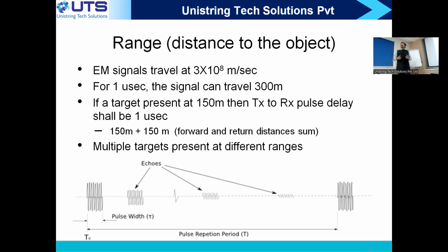At the same time, the more challenging part is that, in addition to targets, there is an annoying, disturbing background, which we call clutter in radar. To handle this clutter and multiple target detection, we get into the signal processing algorithms of radar. Otherwise, a simple time delay measurement would be enough: I send a pulse, receive a pulse, measure the time difference, and I'm able to tell. But it needs to be more complicated, because in a real scenario you have multiple objects, and there is clutter, which is unwanted background that will always be there.